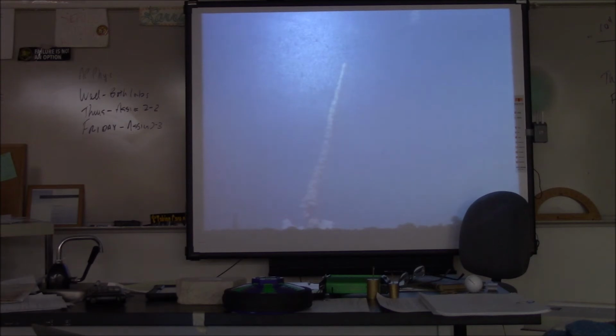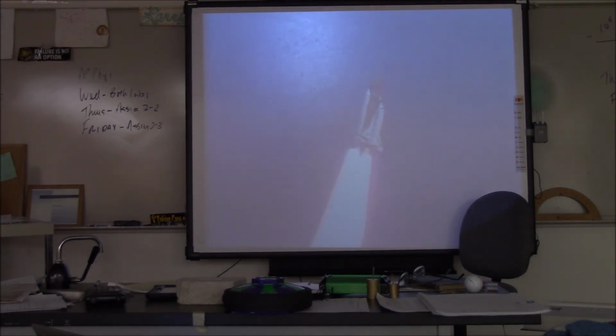After only 30 seconds into the flight, the shuttle is traveling with an instantaneous velocity of 200 meters per second. So that's about two-thirds the speed of sound. At this point, the engines have already expelled 280,000 kilograms of propellant, reducing the shuttle's total mass and weight by 14%. Newton's second law of motion shows that the acceleration has now increased to 8.2 meters per second squared.